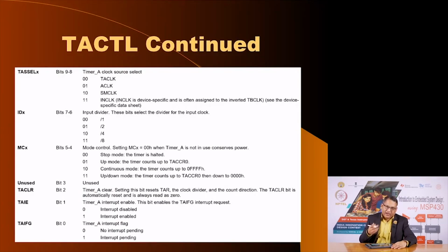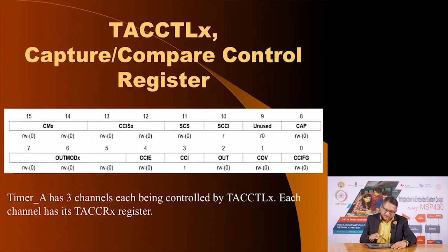I recommend you again to go through these registers. This is the capture control register. These are the bits with which you can decide which mode the timer is going to operate in, whether the capture mode or the compare mode.